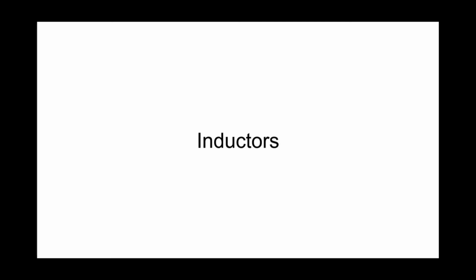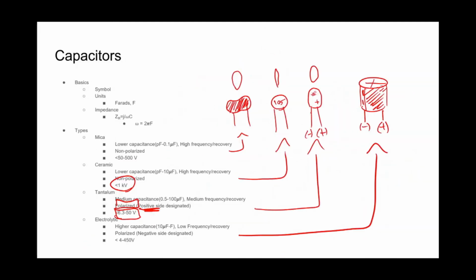Unless, let me check my notes really quick, but I think that's it. One other useful thing for capacitors. Let's go all the way back. So in storing voltage, that's really useful if you had a power supply, right? So if we have this battery here, with our negative and our positive lead, and we draw this off into our circuit, there's going to be some noise there. So if we just add a little capacitor there, just like we talked about with removing noise, or a low pass filter, this essentially will smooth out that signal coming off of that power supply.